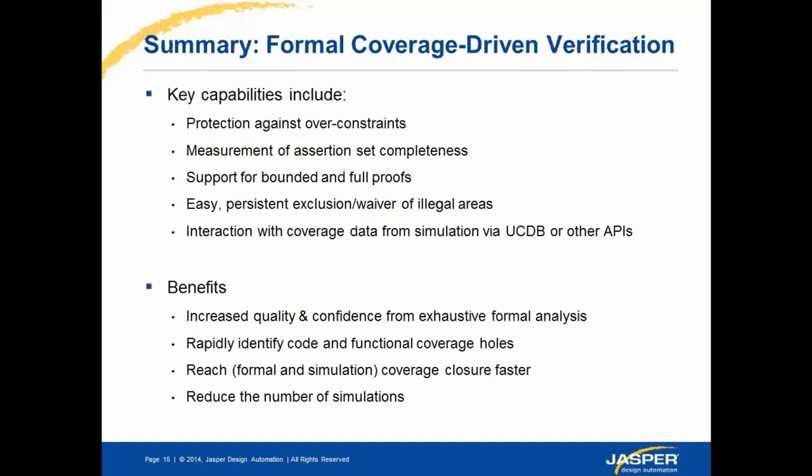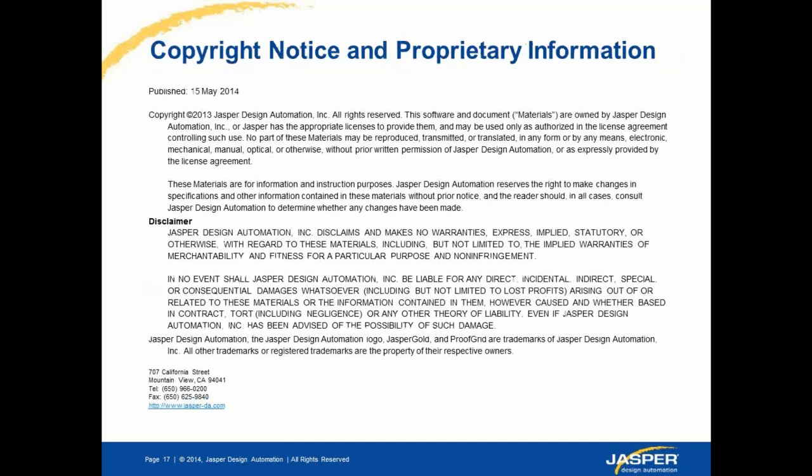Here is a brief summary of my presentation today. Using the coverage metrics, which have been designed for formal by Jasper, you can try to address the problem of property completeness, and you can also get visibility into the observability of your RTL vis-a-vis the assertions. You can use stimuli coverage to identify any potential over-constraining situations in your design, and you can also use the coverage app to help you in the simulation coverage closure flow. And that's it. I'm done.